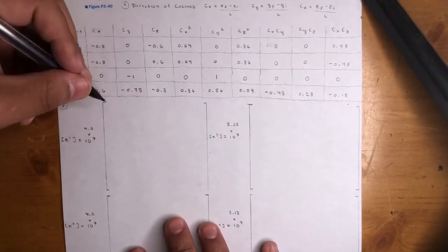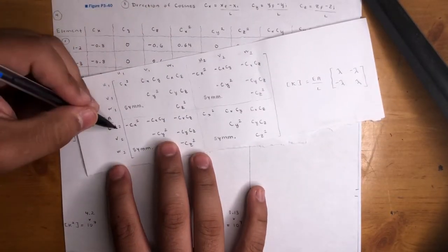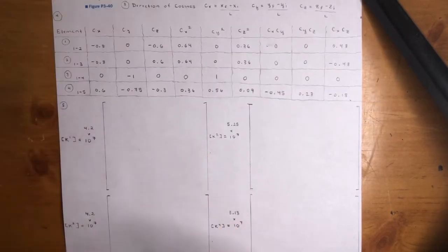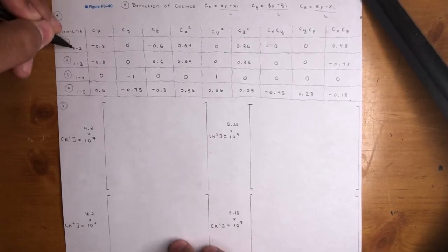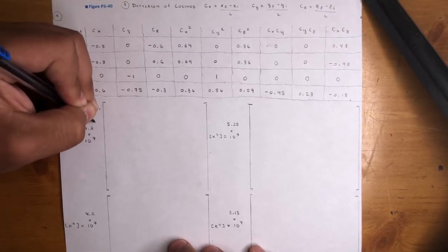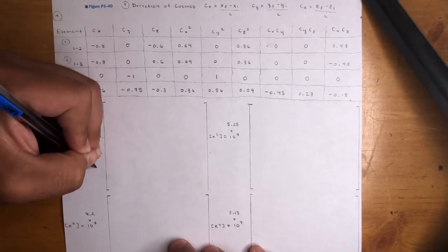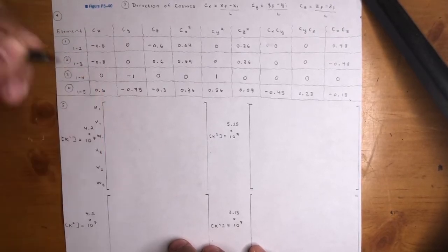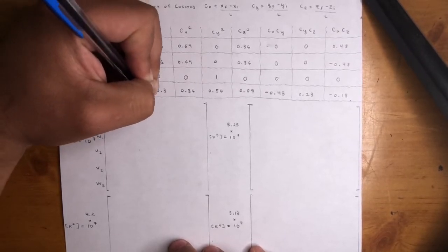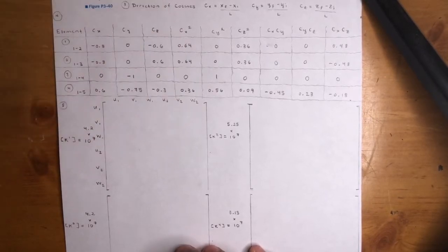The nodes, right? What's going to be on the side, on the bottom? In this case, I just gave it dummy variables, U1, U2, from nodes 1 to 2, and then from 1 to 2 this way. Now, it's the same thing. So for the first element, we went from 1 to 2, so that's the exact order we're going to put them in. We're going to go U1, V1, W1, XYZ, then U2, V2, W2. And same across, U1, V1, W1, U2, V2, W2. So that's the first one.